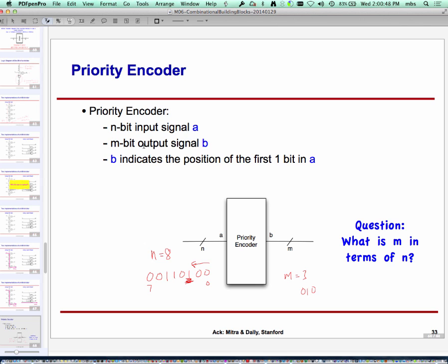So a question was just asked, and I think it was also asked on Piazza, but I just want to clarify. On your circuit for design homework number 2, if any of the inputs are invalid, namely if either temp or the set point are invalid, then the too hot LED should be off, and the temperature display should say minus minus, the middle segments being on. So that means if temp is 000 or set point is 000 or both of them are 000, then your input is considered invalid.